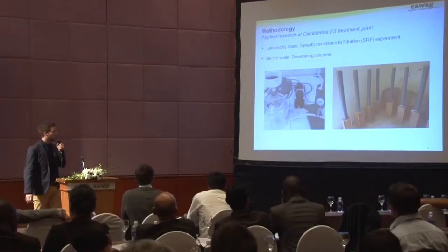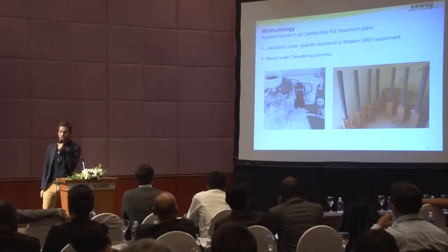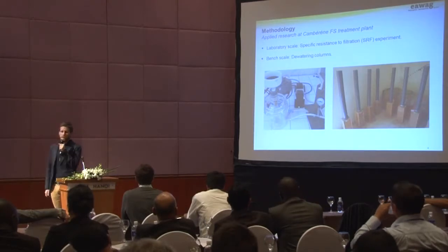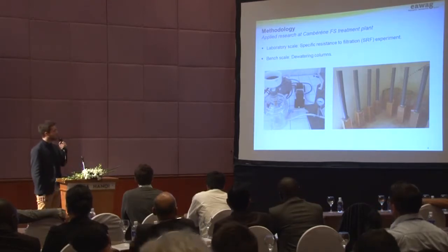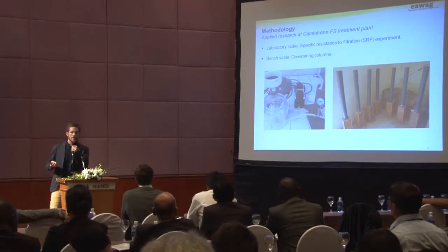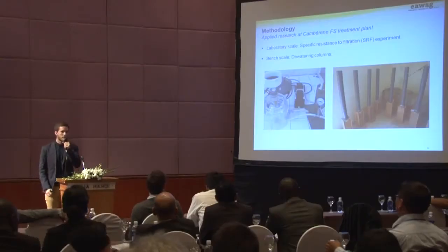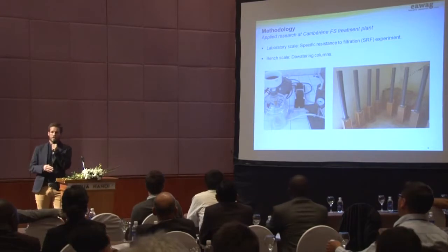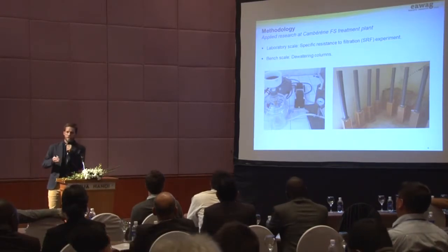To assess if these conditioners can really improve dewatering properties, we're conducting lab and bench scale experiments. In the laboratory, we're looking at specific filtration, which is measuring the resistance: how difficult is it to dewater, to get water out of the sludge. This is done by adding conditioned sludge into this funnel and then sucking it through the filter. So we're comparing unconditioned sludge, conditioned sludge, and also different dosages.